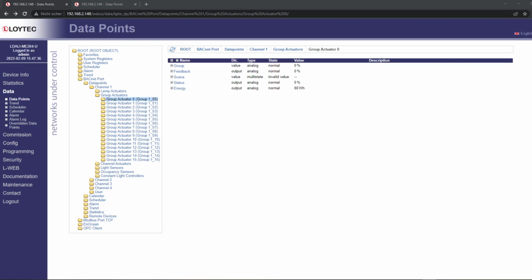Application side, the value can only have been written from our DPAL layer. How I came to this conclusion will be seen later on. The value therefore must have been written via the network, for example BACnet or OPC, or on the data point itself, for instance via the WebUI, or also a local connection, or a math object.